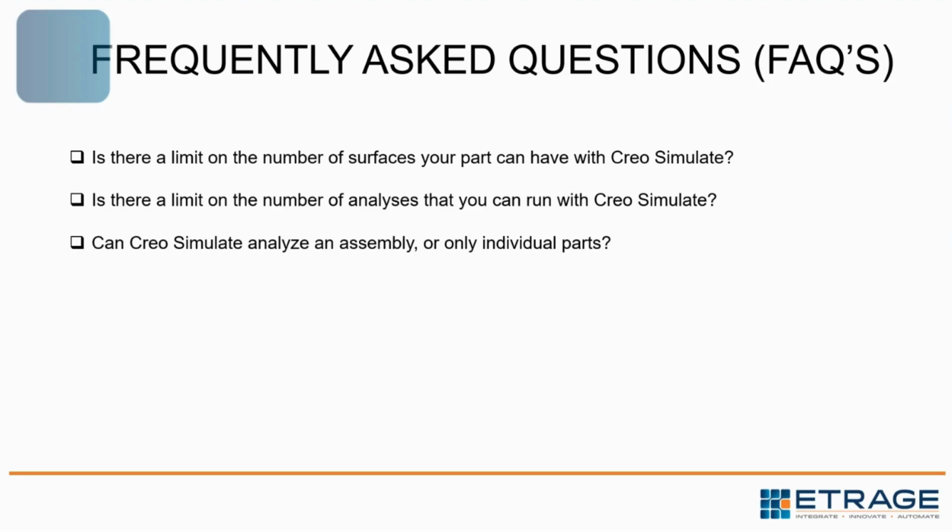It'll still eventually solve, it'll just take a much longer time. It'll slow down your solution time. And that's where we can get into making sure your computing specs are adequately sized to handle the size of the geometry that you're trying to simulate. But again, there's no hard-coded limit set in the software for mesh or node counts.